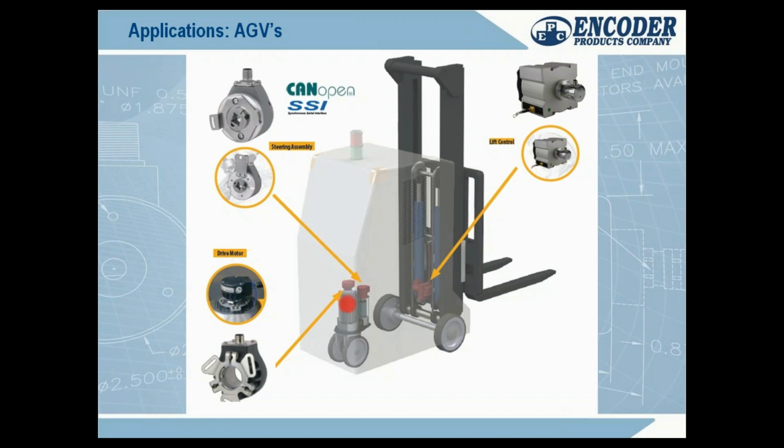So that would be installed here. Right next to it, we have a steering axis motor. This rotates the caster. We need an angle. And for safety, we can't get that angle off pulses. We need that encoder to deliver the true angle, power loss, skipped, whatever, every time. So we put an absolute encoder on the steering axis of this AGV to give an angle of where it's steering.